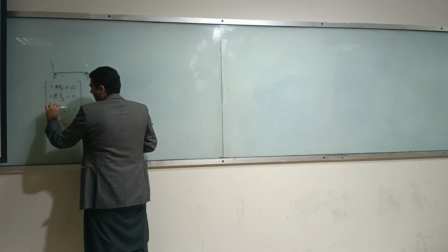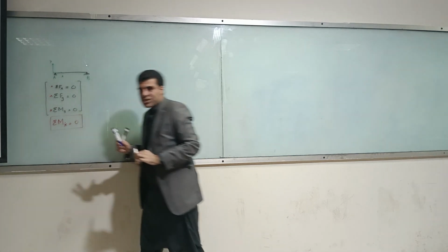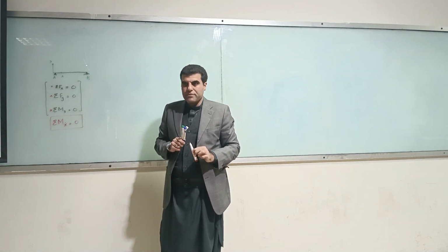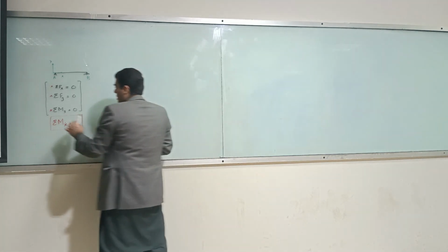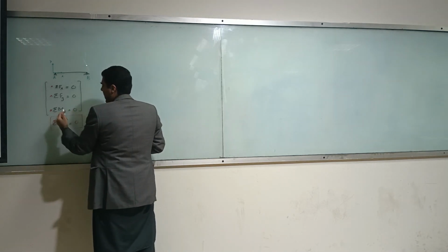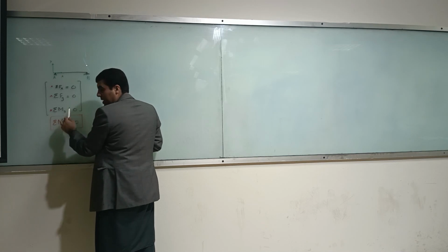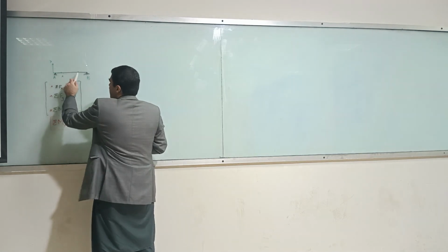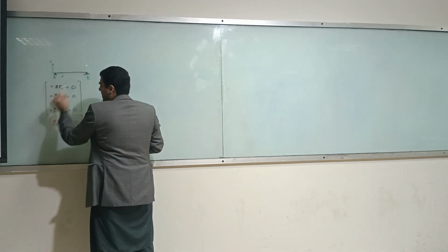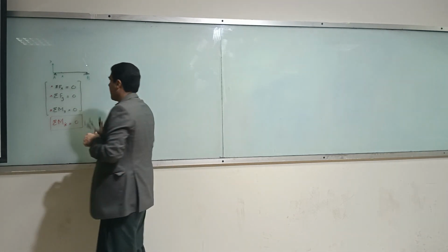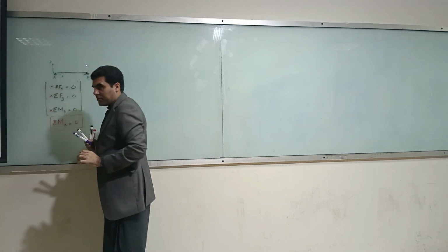And the Mz is actually your flexure moment, isn't it? The moment in z is also called flexure moment. In other words, the moment Mz about a certain point will cause flexure stresses. So these are the 3 equations which have to be satisfied in order to get your reactions.